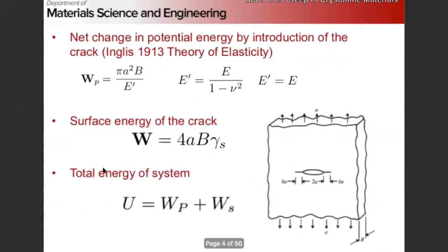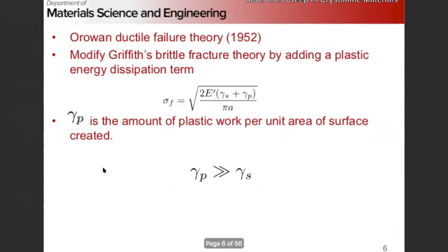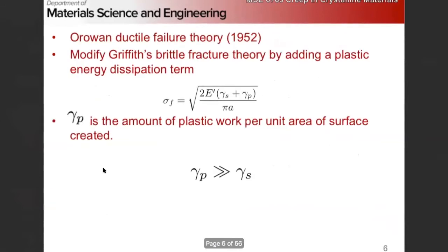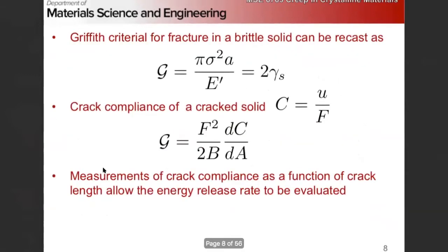Right, okay, so this is just this here. That's the stress required. This is, right, this part of Griffith's criteria, if we just move this over to this side, when these two are equal, right, when this term is equal to the stress, that's when we're going to have fracture. So it's not recast, it's just rearranged, right?